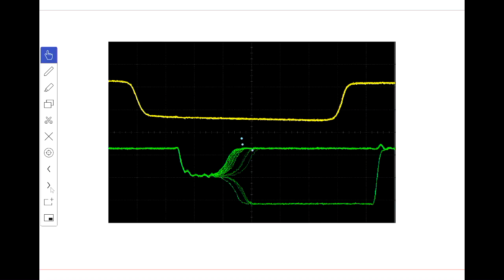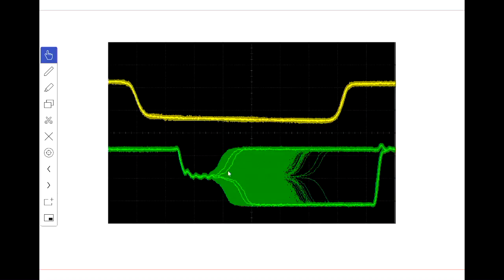And the textbook has another picture over a longer time, and you can see that the time it takes to resolve, to come out of the metastable state, changes. Sometimes you come out of it quickly, sometimes a lot slower. Once in a billion gazillion years you might not come out of it for quite a while, but almost always you come out of it fairly quickly these days because flip-flops are very high speed. The two inverters in a loop have very high gain, so as soon as you're a fraction above or a fraction below halfway, you quickly run off to the extremes. So you may enjoy looking at that part of the textbook.